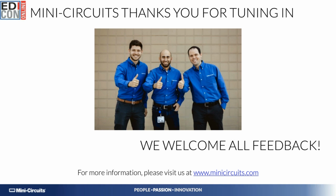The question that we will have to pose afterwards is how much insertion loss can we afford? There's a theoretical relationship between the bandwidth of the filter and the insertion loss: as the percentage bandwidth gets narrower, the mid-band insertion loss on the filter will increase for the same order and the same topology of a filter. So the short answer is yes, and the counter question will be, how much insertion loss can we afford on a system level?